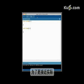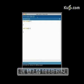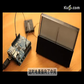To change the pulse width, we use the Arduino function analogWrite, with the first parameter being the pin and the second one being a value between 0 and 255. I've hooked up my meter to pin 6, and let's give it a value of 128. That should put the needle right in the middle.